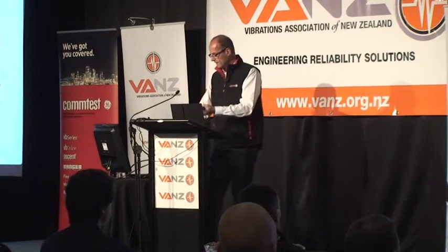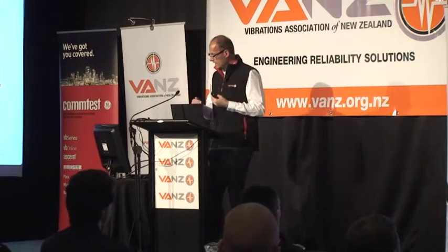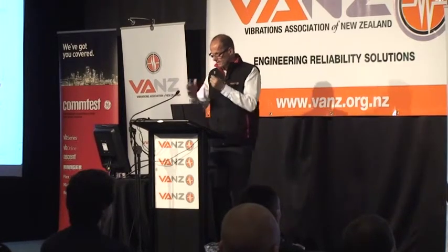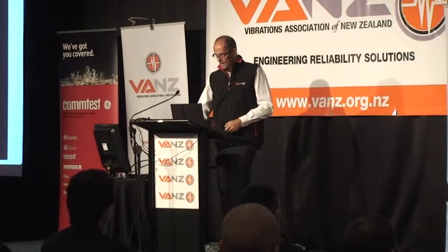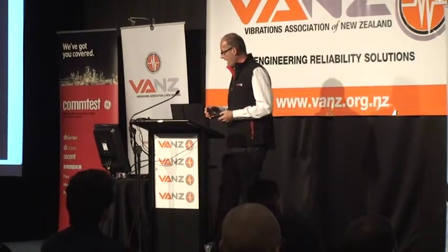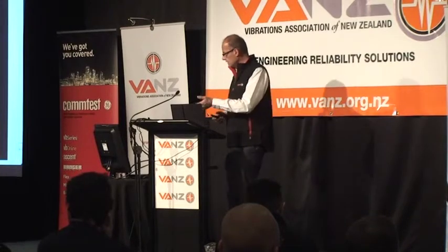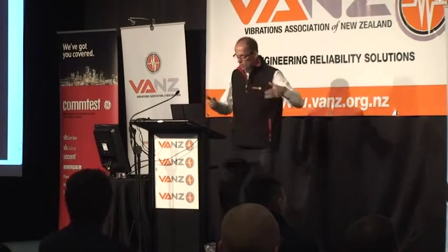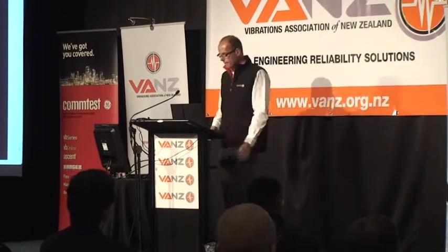When bearings start to fail, we see their magic frequency. This is for damage on the outer race, but we get these harmonics. And there's lots we could talk about with each of those. I think part of the key to all of this is actually understanding what the machine is going through when these fault conditions exist. So a simple one, like static unbalance, we've got that motion which you've seen a few times, and there it is animated.